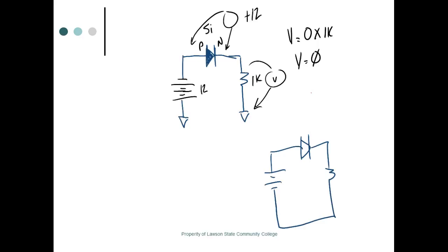So that means you get your hand in that metal box, right, you understand. It might not kill you, but it sure will burn your hand. So remember, when you measure across a switch, if the switch is closed, you should get 0 volts. And that's true of a circuit breaker, too, by the way. So that's the way you can check a circuit breaker.